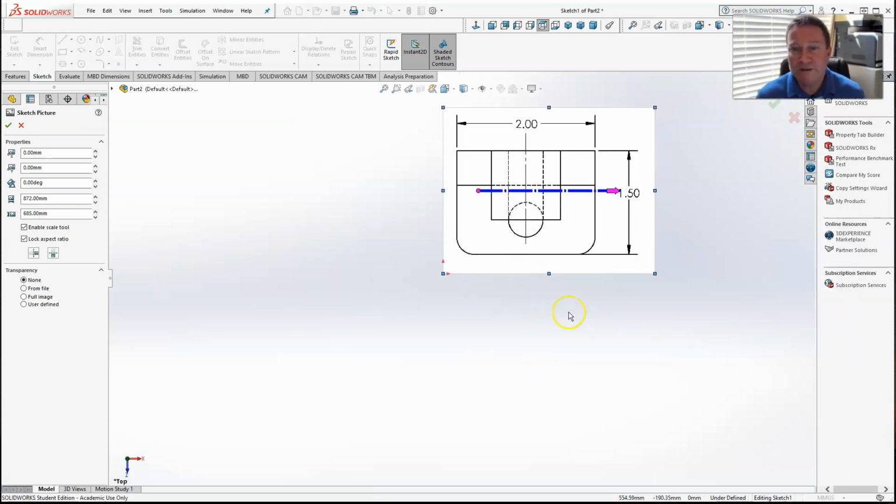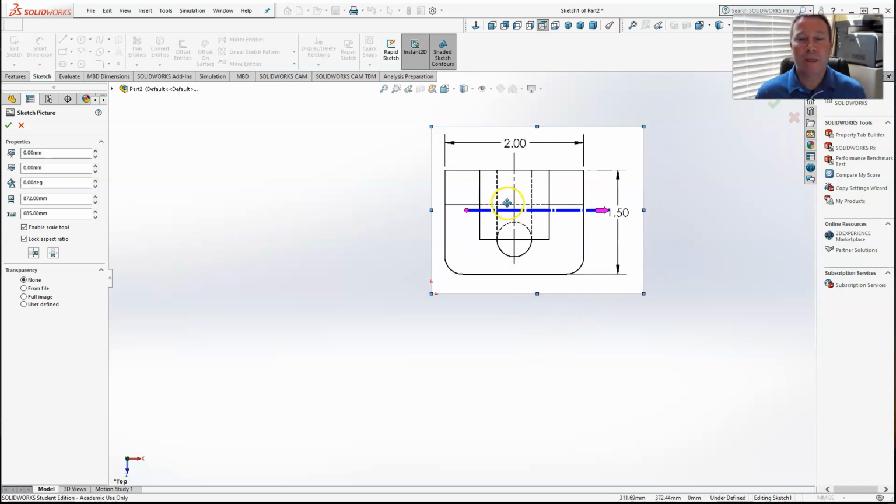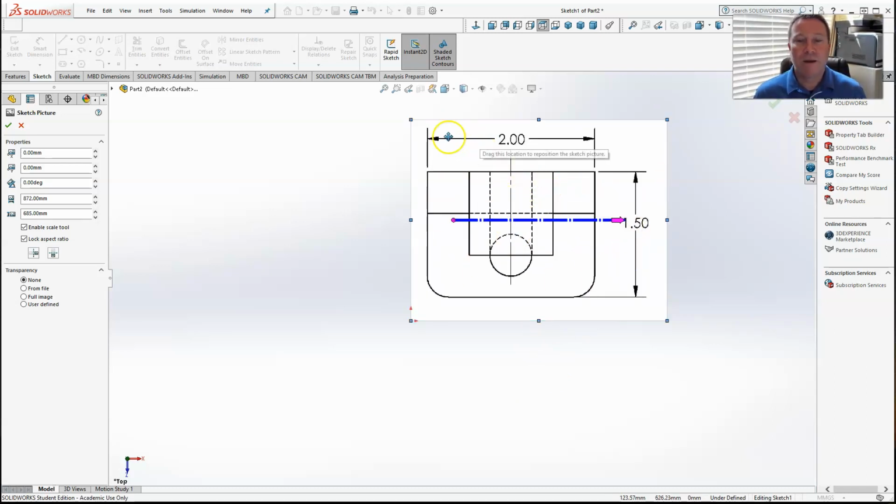One thing I learned by doing this exercise a few times, we're going to scale the picture. You always want to pick the largest dimension to scale the picture off of, because you can get a more accurate scale. If I knew the dimension of this circle, let's say it was a ½ inch diameter, or any other small component, maybe half the size here. If I only knew this was 1, but I can assume it was 2. But if I had a smaller dimension and I scaled the picture off that, my error could be a lot larger. So pick the largest portion.